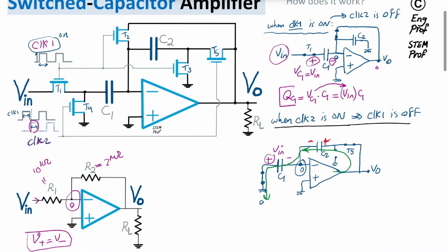So with this polarity, because we are charging capacitors up given the direction of the current, we have QC1 moved over to QC2, assuming that whatever practical cap at the output of the op-amp we have is negligible compared to the sizes of C2 and C1. So those are important practical considerations. Now we just consider that we have C1 and C2 in this circuit. So Q of C1 should be equal to Q of C2, which means